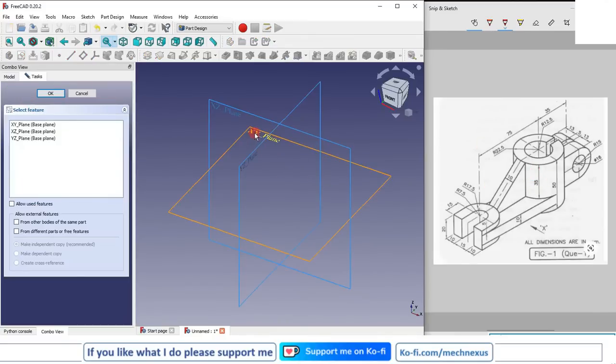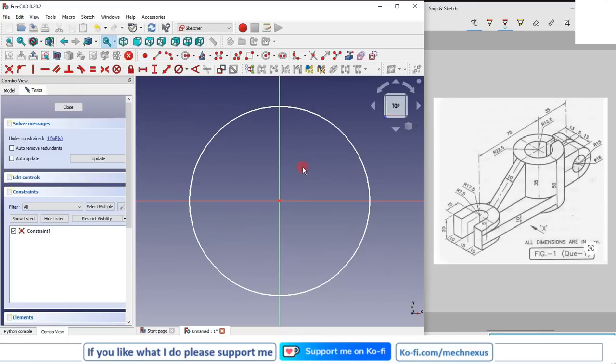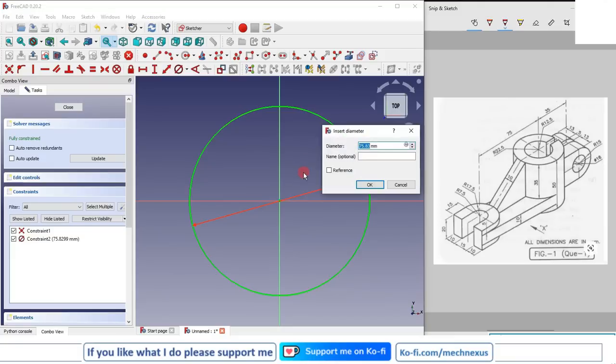I will select this XY plane as my base plane, and here I will select the circle and I will draw a circle. Here is a radius R22. This cylinder will be our base feature, so I will select on diameter and I will give my diameter, which is a 45.